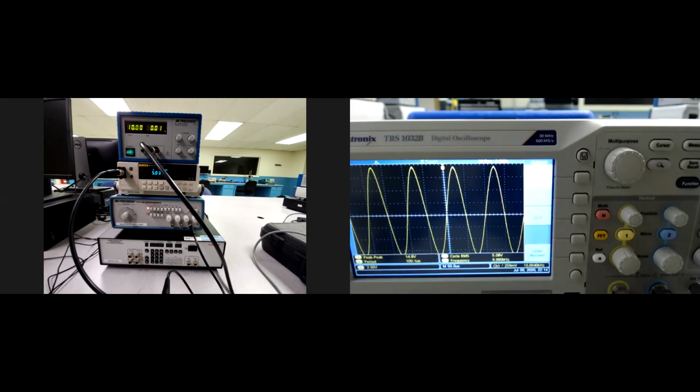Each signal can be comprised of an AC and DC component. If only the AC component of the signal is to be monitored, the oscilloscope should be set to AC coupling. If both the AC and DC components of the signals are desired, the oscilloscope should be set to DC coupling. The objective of this assignment is to introduce channel analysis using the oscilloscope and examine the effects of AC-DC coupling. Okay.